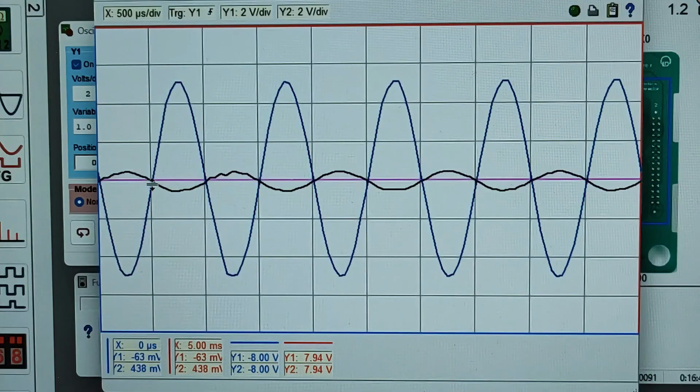These two waveforms are separated by half a cycle. You can see it from here. The blue waveform is going up here, and the black input waveform is going up on this side. So you can see there's half a cycle difference. From here to here, there's half a cycle. So if we use 360 degrees as the reference for one full cycle, and the separation is half a cycle, therefore the phase relationship for our inverting operational amplifier circuit would be half of 360 degrees, which is 180 degrees, clearly shown on this oscilloscope display.